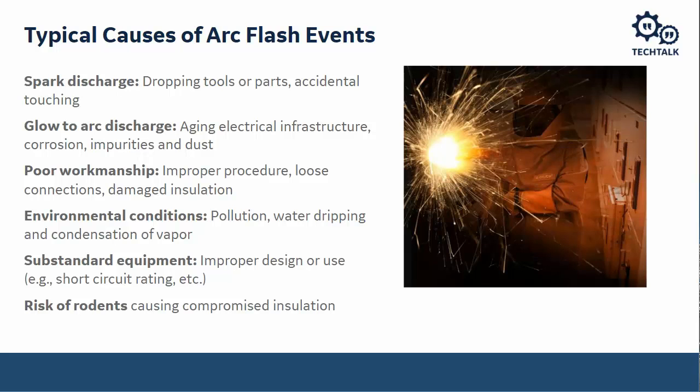I've seen some temporary conditions that had tags on them from 1979. So sometimes temporary lasts a while, but that's not a good thing. Then there's the risk of rodents. Vermin gets in there. That's always an issue in switchgear. Some kind of critter getting in there and creating an arc. Bad news for them, bad news for you if you're near it when it happens.